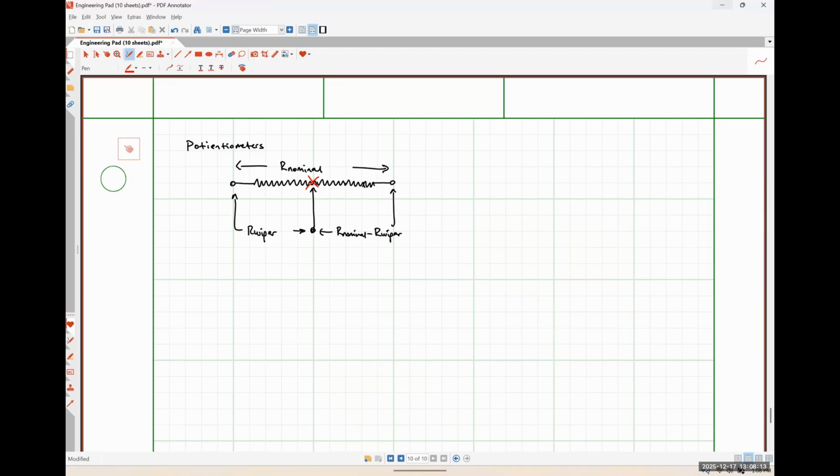So if you're going to use a potentiometer, and I've even seen graduate students make this mistake, realistically, you probably don't want to have both of the outside terminals actually connected to anything in your circuit, because it's just going to look like that nominal resistance. So you really only want to use two of them usually. And it's a question of, do you want the resistance to increase when you turn the knob clockwise, or do you want the resistance to decrease when you turn the knob clockwise?